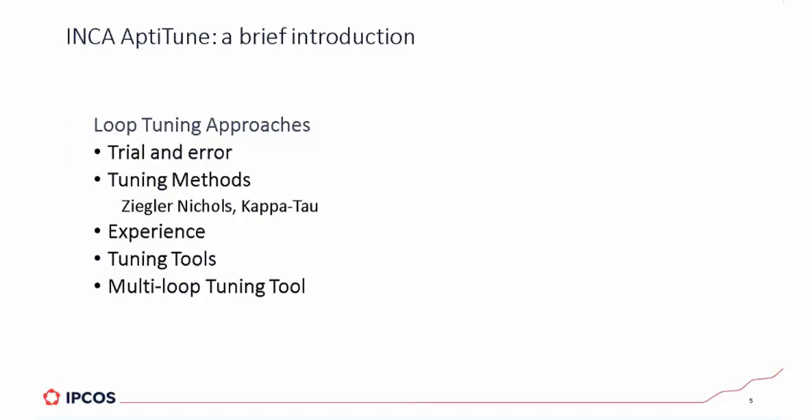If you are tasked with the assignment to tune the loop, to improve the tuning of a certain PID loop, then your first experience might have been that you do that using trial and error. You increase the proportional action a bit and see what that does. Find that the end error doesn't go to zero, so you increase the integral action a bit. Then you become enthusiastic from the results and you increase things even a bit more. Things start to oscillate, may even go out of hand. And that might be a trigger to say, well, maybe a more structured approach is appropriate.